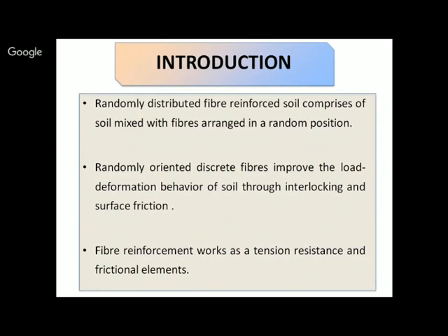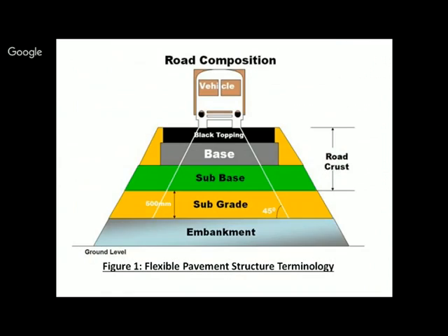These fibers are mixed in soil in order to increase the shear strength and the tensile strength of soil. Randomly oriented discrete fibers improve the load deformation behavior of soil through interlocking and through surface friction. Fiber reinforcement works as a tension resistance and as a frictional element.